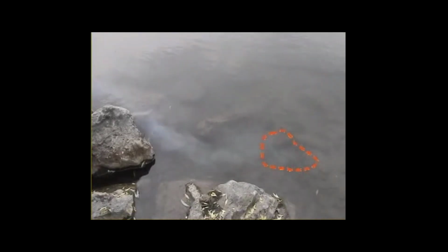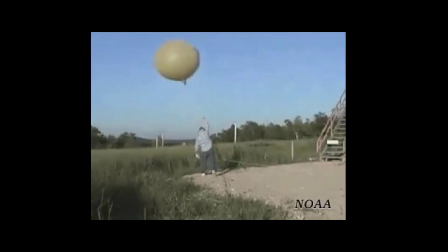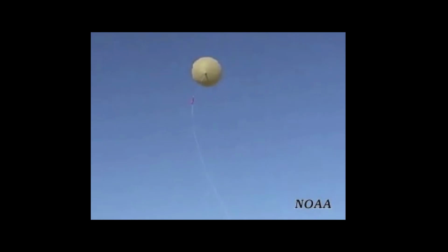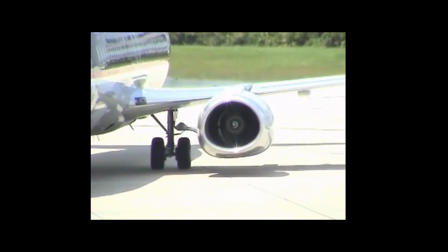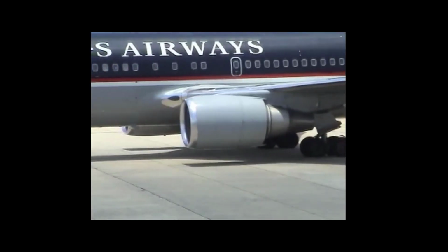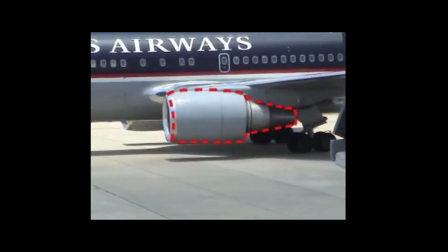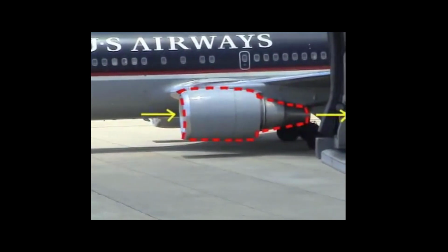The Lagrangian approach works best, for example, in meteorology, where a weather balloon drifts along with the prevailing wind. This reference frame is inferior to the Eulerian approach, however, in treating the airflow through a jet engine. In this case, a control volume is fixed to the jet engine with air flowing through it.